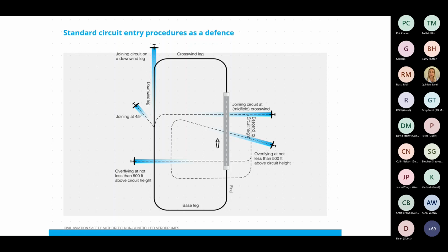Yes, air transport operators like to do straight-in approaches. There are advantages for them to be able to do that. As we've seen in previous webinars, some of those aircraft are difficult to see out of, like the Q400s, the Saabs, and the bigger aircraft, the 737s and the Airbuses that might operate into and out of places like Mildura and Ballina on the northern coast of New South Wales. They can be difficult to see out of, and an Australian approach does provide them with the advantage that all of the traffic that's likely to conflict with them is generally going to be in front of them if they're established on final approach for the landing runway. So they do like doing those types of approach.